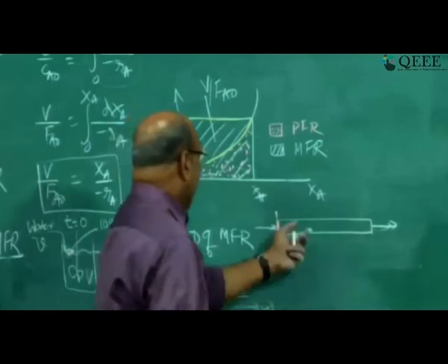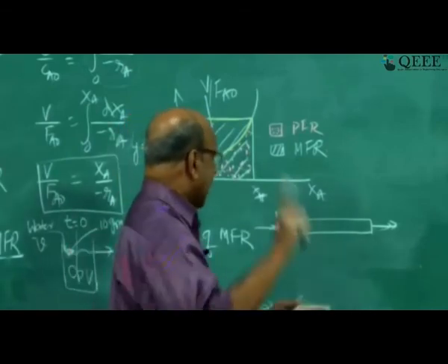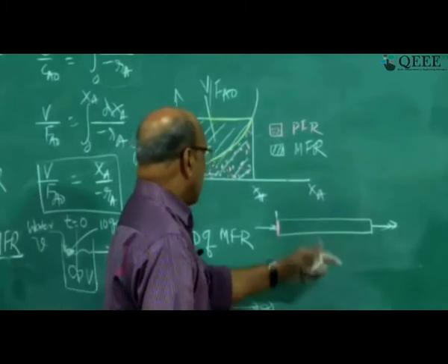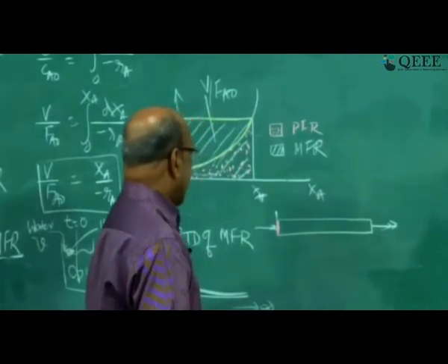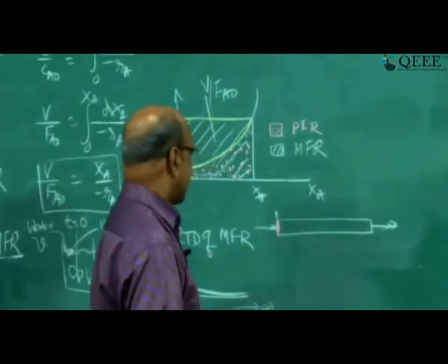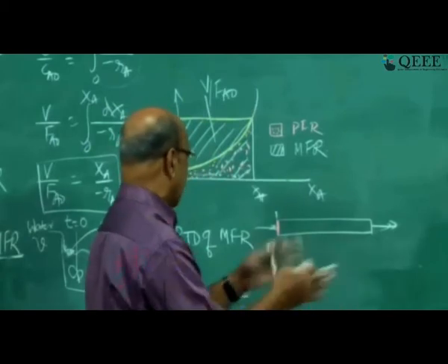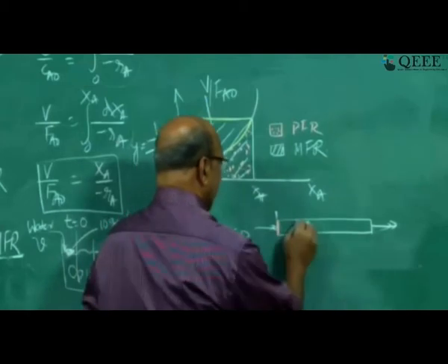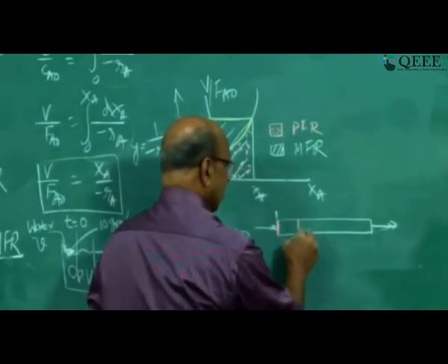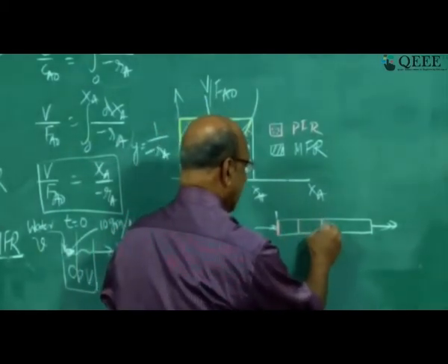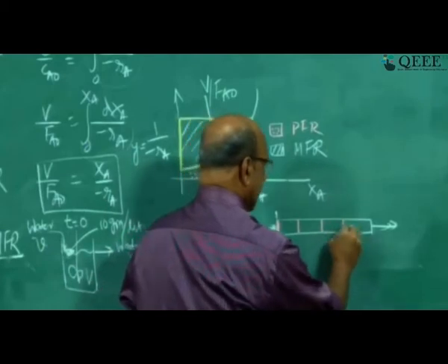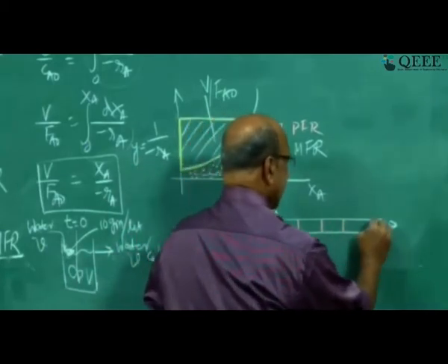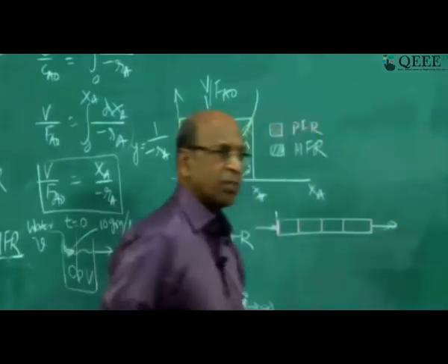So now, by definition axial mixing equal to 0, radial mixing equal to infinity, and each and every particle should spend exactly the same time, because of all these conditions it will automatically do that. So now when I look at this disk, it is not disturbed at all. I can see it here at 1/4 of the time, half of the time, 3/4 of the time, and finally the disk comes out as it is.